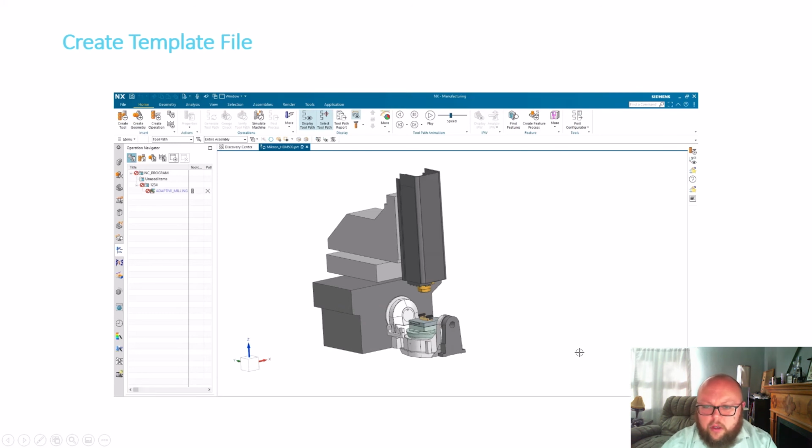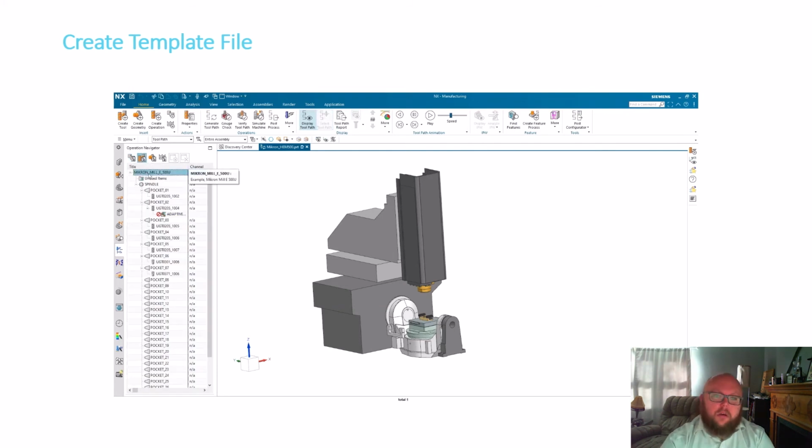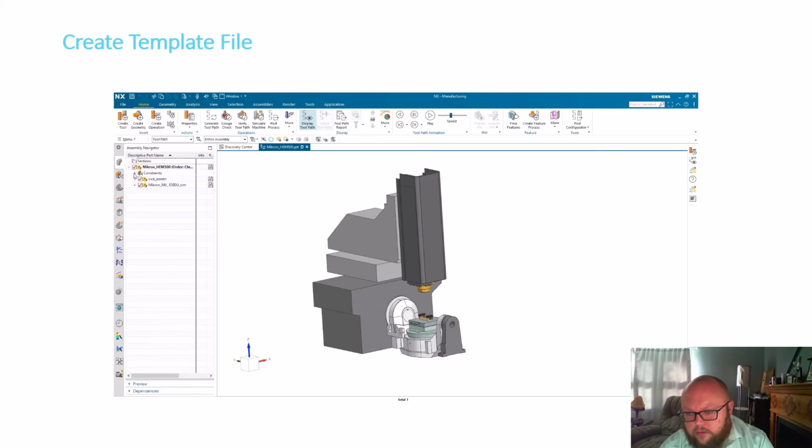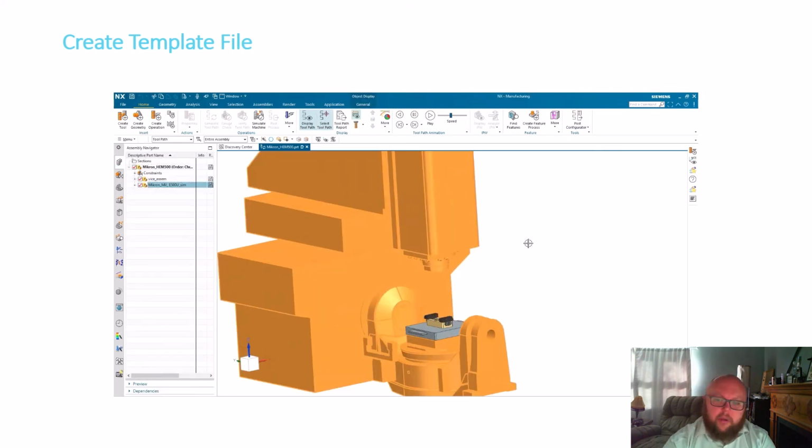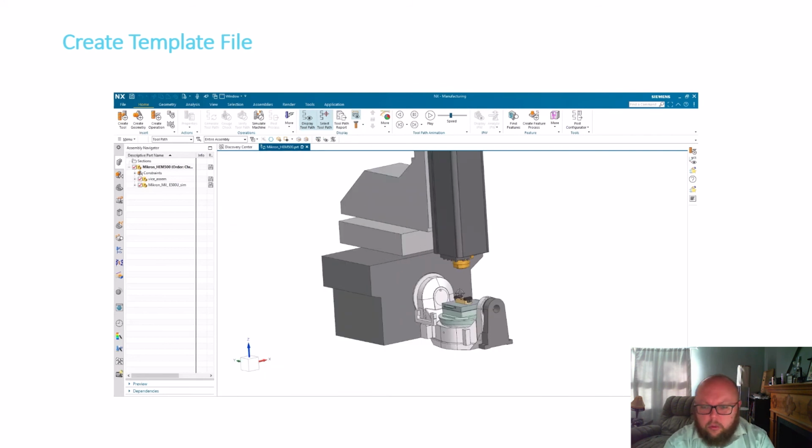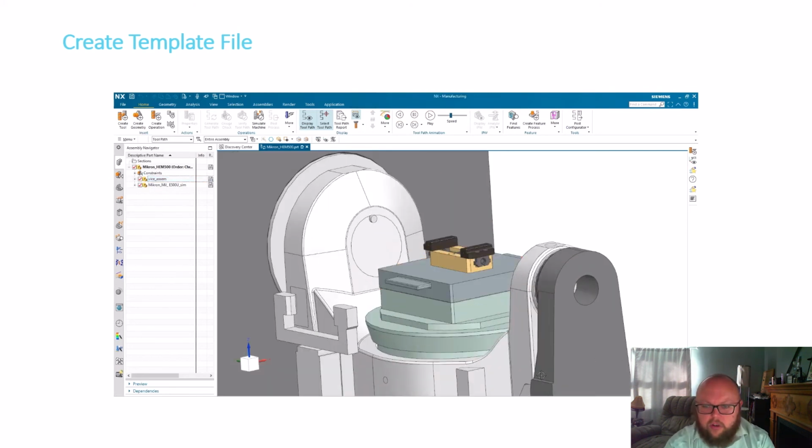In this case, we can see that we are looking at a machine, and it's got a quick change table. This happens to be a Dynafix table, but that whole palette can come in and out of the machine. And in this scenario, in our setup, we have a vice on here. So we can have a number of different setups available in our templates. We could have a single vice setup like we're seeing here. We could have a dual vice setup for doing multiple ops. We could have a chuck, grid plate, maybe a little tombstone or other custom fixture that we used oftentimes. Again, goes back to your application, what really makes sense. You can go ahead and do those things based on your needs.